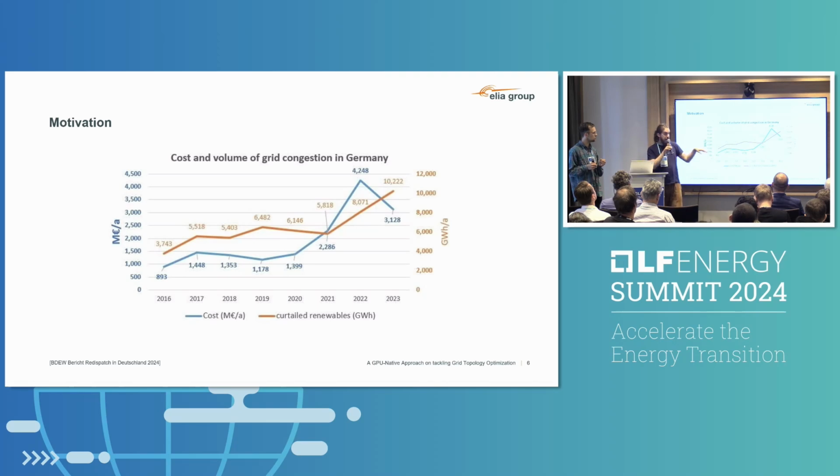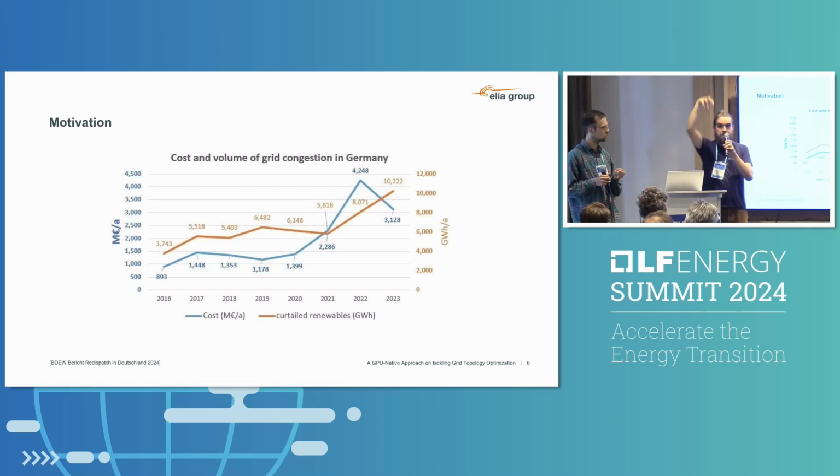So in grid planning, that's a very nice separate idea, that we could extend this idea. I mean, if you look at grid planning from a bird's eye view, it's basically a topology optimization, just that you don't remove lines and you don't split bus. What you do is you add lines, you increase the capacity on lines, you add equipment to the grid, like all sorts of things. So from a bird's eye view, it's a topology optimization, and we believe that the same idea that we did on topology optimization for congestion can be applied to the process of grid planning.